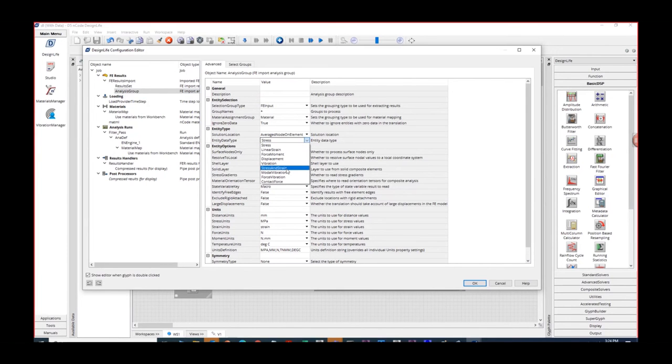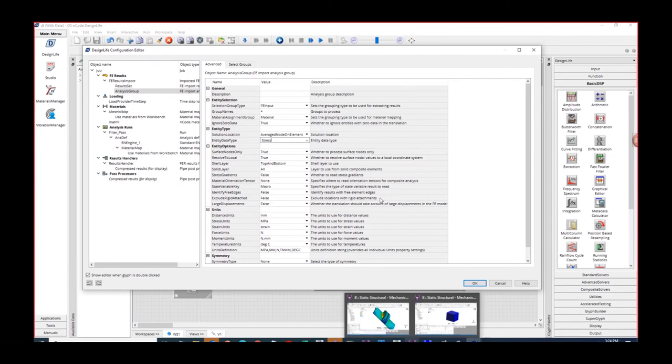We have to carry out a nonlinear material analysis in Ansys Mechanical, including a plasticity material model, so that both the stress and plastic strain data will be processed for the fatigue calculation, which will not use any plastic strain correction algorithm.